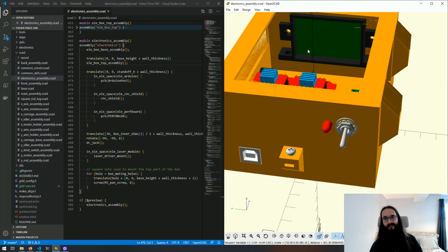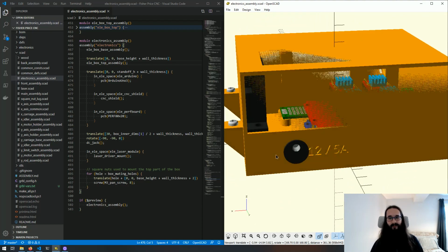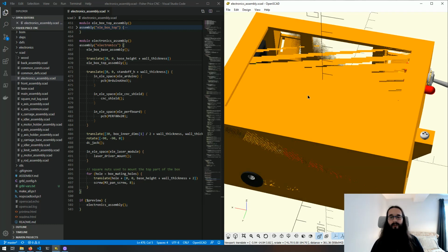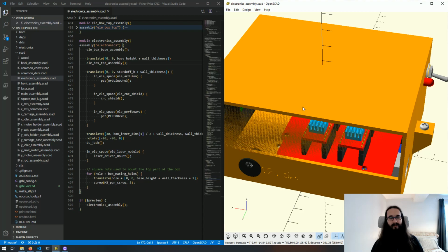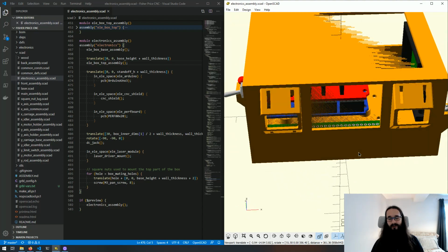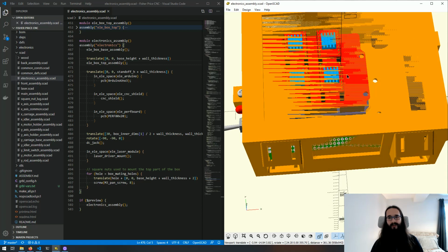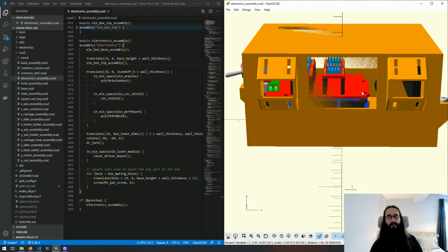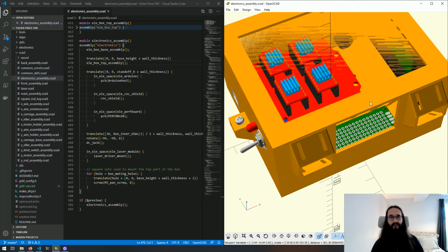I've shown an issue where, when the Arduino's in reset, or actually I've discovered when the Arduino's not powered and the 12-volt power is given to the rest of the circuitry through this barrel jack, which is a panel mount barrel jack, and the wires are routed into there. When only the 12-volt power is supplied, the laser is on. It's continually on without the Arduino inhibiting it. So it's not really a fail-safe design,